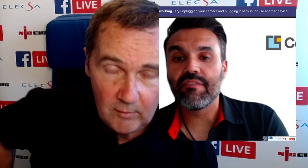Agree with that as well, Dan? Spot on. Every time, I came from an industrial background and always went straight to the manufacturer. There are a couple of well-known manufacturers out there that have fantastic and excellent technical databases, and if you give them the model type of the MCCB, they'll ring you back with data on it. And to be fair, for each setting of the MCCB there are different Zs values, so they go properly into it, and you can really get exactly what you need. So again, manufacturer data, internet is a wonderful thing. Okay.